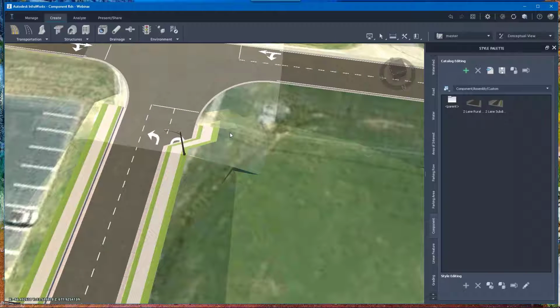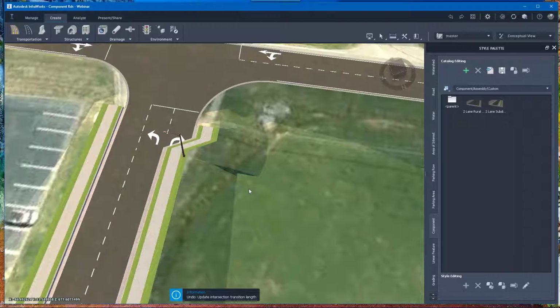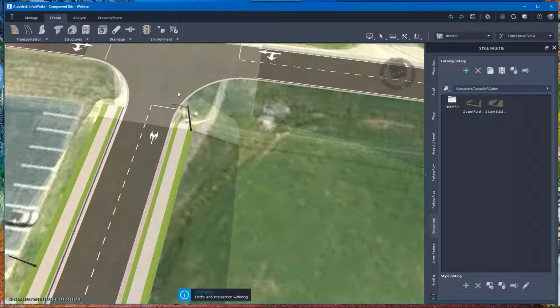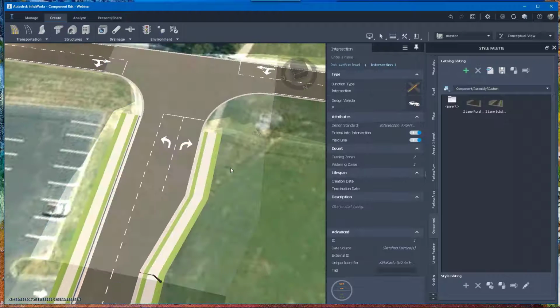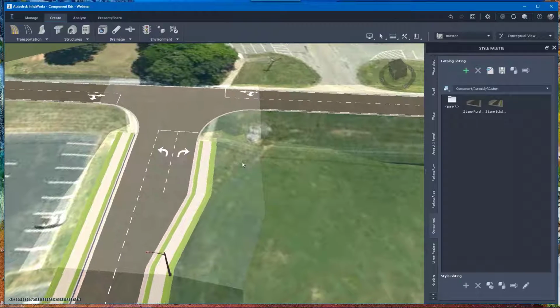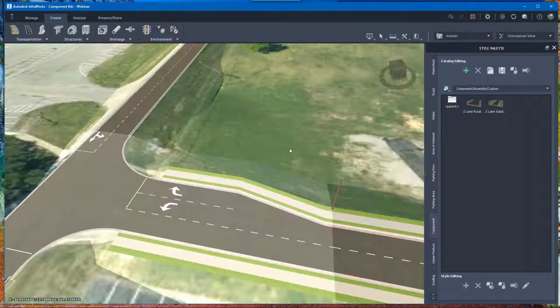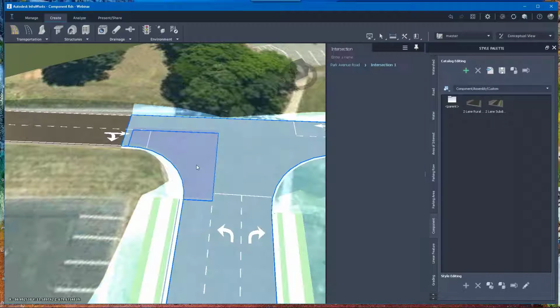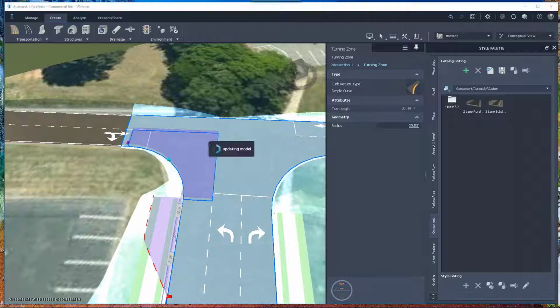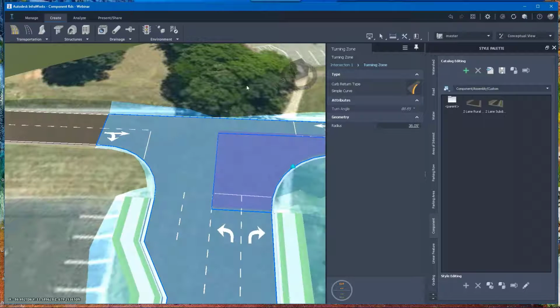Oops, hold on. I got a mess. So we can pull this back so we can see our taper. We can also see what's going to be approximately 50 feet for now. We're going to drop it in. It automatically changes our sidewalk. It adds in our turn lane. We may want to do the same as far as an entrance. And again, just make the adjustment here.